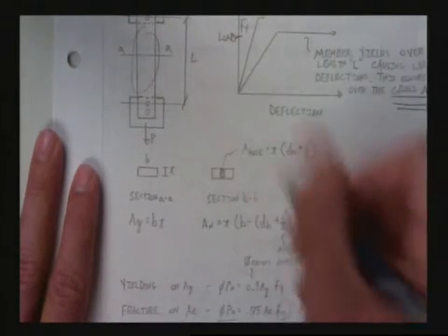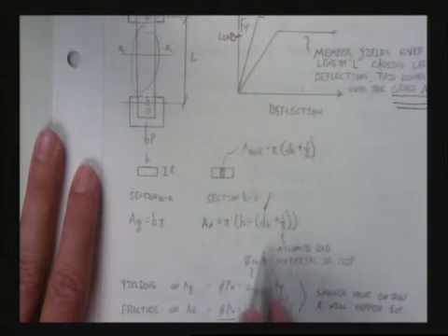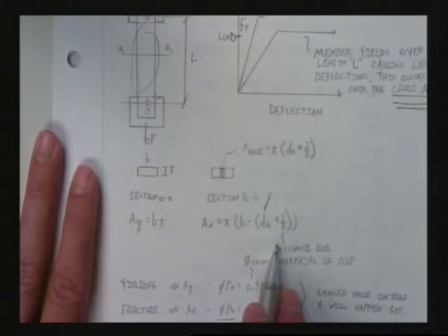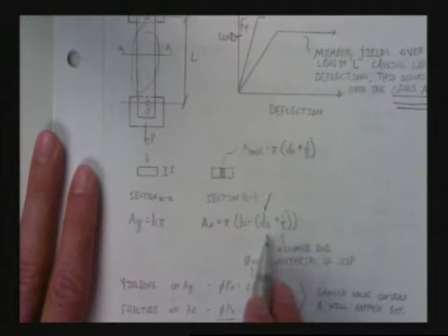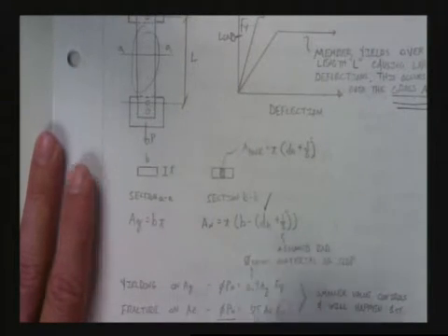Now, every time in this class, when we take out the holes, we're going to add 1/8 of an inch. Why do we do that? Because it's slop, right? When you drill the holes, there's going to be some damage done to the side. Some people like to use 1/16 of an inch. A lot of people in practice like to use 1/8 of an inch. Why? Because it's conservative, right? It's conservative. Okay? So oftentimes in this class, when we're subtracting out the diameter, we'll take out another 1/8 of an inch for the slop. Okay.